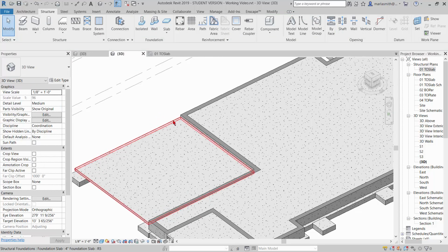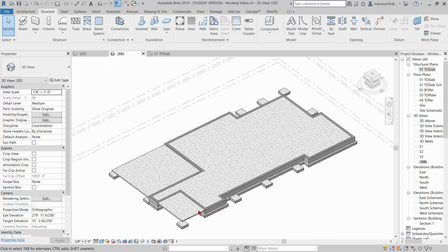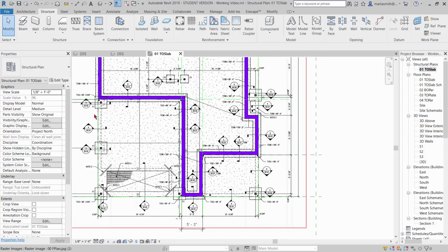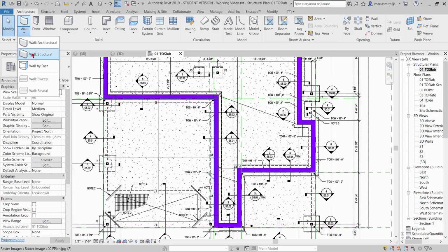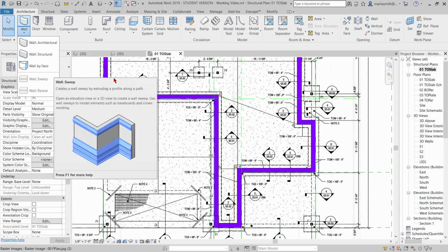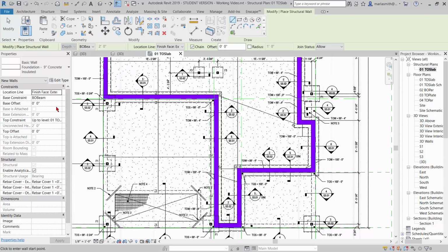The other thing we'll probably want to do is go ahead and put the foundation wall underneath this and underneath this, which doesn't have a footing running below it, it just has a straight foundation wall. So we can go into our top of slab, and I'm just going to go to architecture, wall, or actually let's just do this, it would be easier. I'm just going to pick this guy and create similar. The only thing I want is for it to be -10 inches in both the offsets for the top and the bottom of the wall, because it's 6 + 4 for this guy right here.